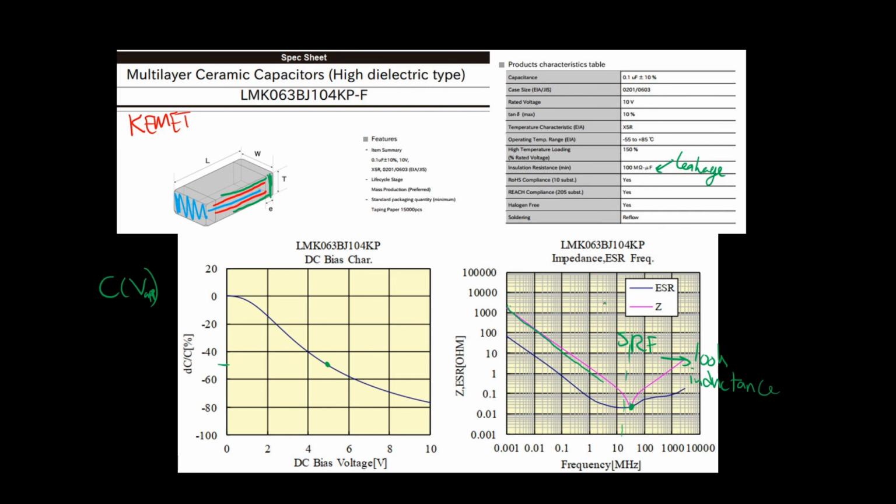On this side, right, it looks like a cap. So there's a frequency range over which caps are actually useful as caps, right? Beyond the self-resonant frequency, that no longer holds. And you can see the ESR here, right? So they said 10%. So the ESR max is 1/10 of the impedance of the cap, right? And that's what you see here. This is less than 10%, and that decreases up until a point, right?